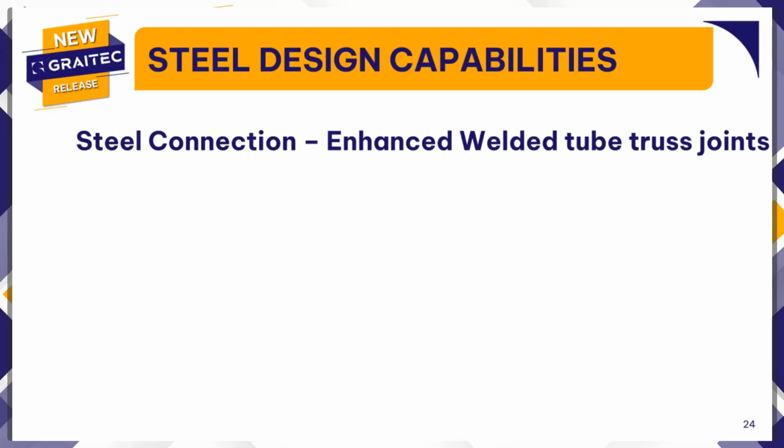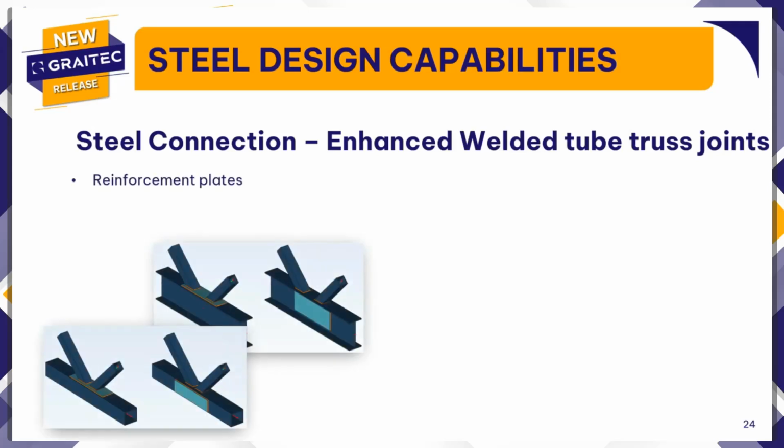And now about improvements related to steel connections, and more specifically to the steel connection module. I'll mention 3 improvements to the welded tube truss connection. First, we introduced the possibility to define additional reinforcing plates, which can be defined horizontally or vertically on the truss cord. Such plates can be